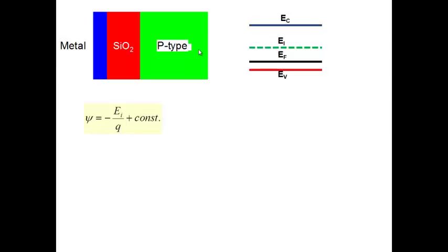What does it mean? If I have no electron current, Fn is flat everywhere. Same I can write, Jp is p mu p dFp by dx. I don't have any current. The hole quasi-Fermi level is flat everywhere, right? So you agree that the electron quasi-Fermi level and the hole quasi-Fermi level will be flat. Why will they differ?